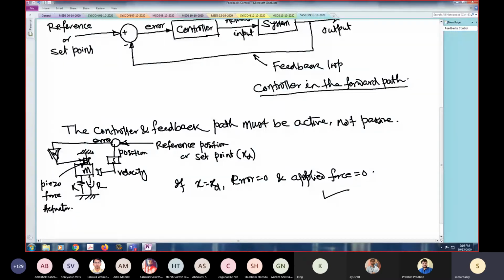What does that mean? That means, okay, let's model this part as a bond graph. Let's say we have velocity sensor, some one junction, I, C, R. Then from here, we are having a flow activated bond. I am not putting the sensor as it is. I am completing the entire loop. So we have a flow activated bond, and then we have some kind of integrator, let's say.